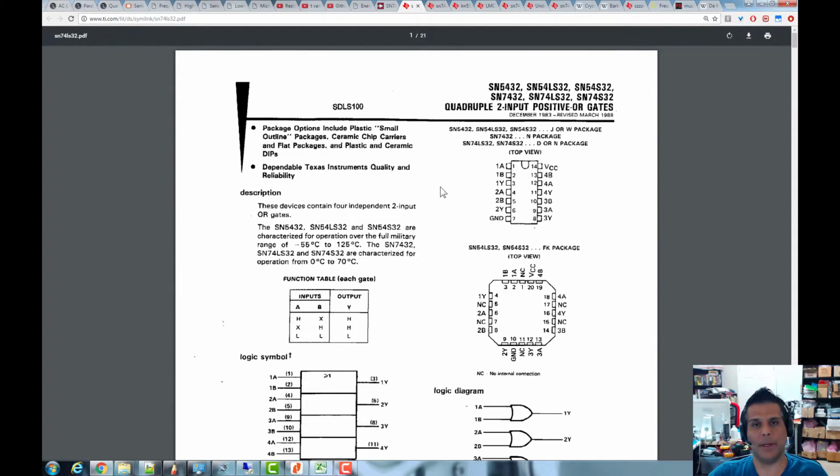So if we can do something that uses more OR gates, we want to do that, because we're going to have faster propagation delays and we won't have to wait. Those AND gates are slower. So this is why knowing this stuff is very, very important if you want to do crazy level optimization.